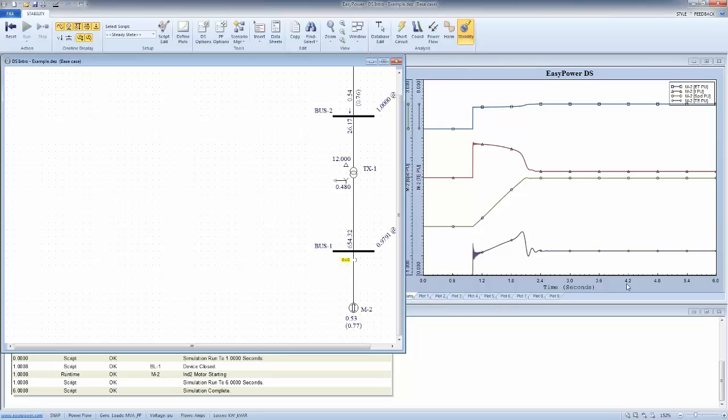What you get from load flow when the breaker is closed are these values here. What you get from the load flow when the breaker is open are these values here. But what you don't get, and might be missing, is how it goes from this point to this point. That is dynamic stability. So I think by now it should be very clear why we should switch to dynamic stability and when, depending on what type of study we run. I can give you numerous examples.